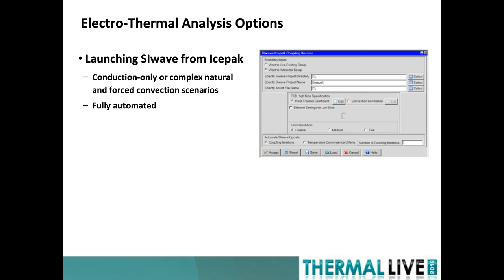And so we have another question on the VIAs in the PWB. The VIA modeling, is it available for all of the components, or is it limited to only a few components in the simulation? So the VIAs will come in with the ECAD file. You would set up the VIAs in your PCB layout tool, and whatever you set up there, you will just import into IcePack as an ECAD file.